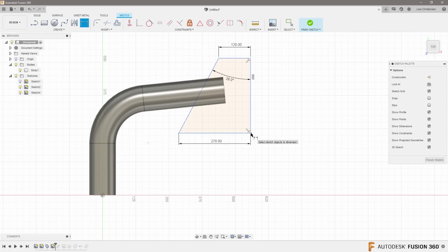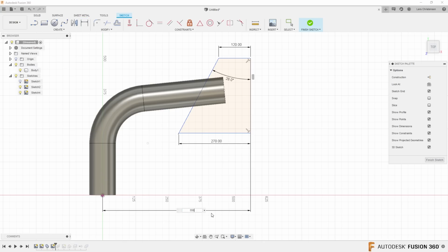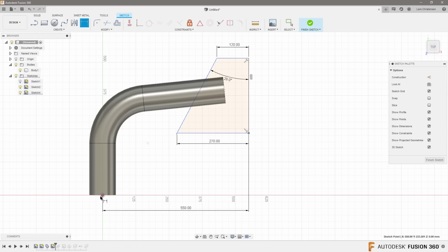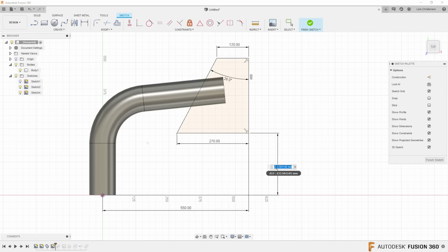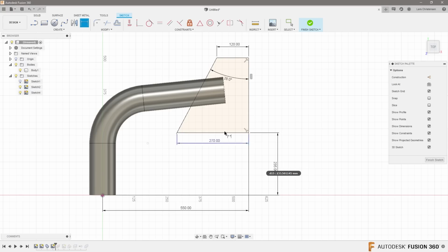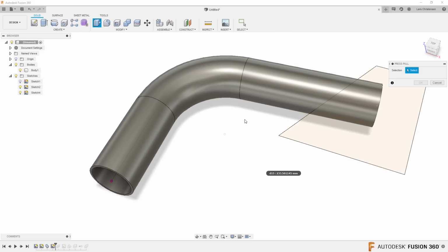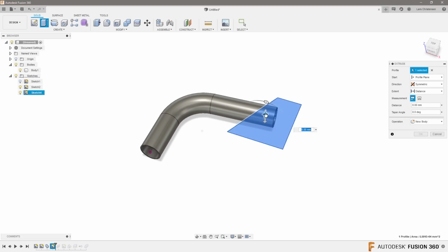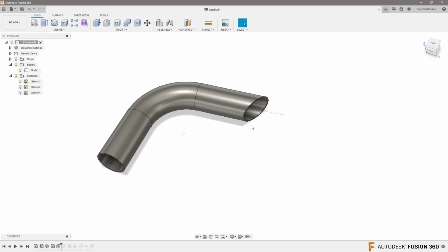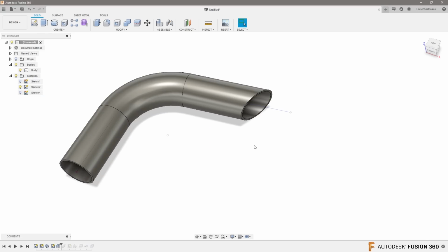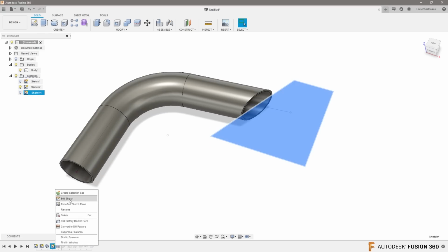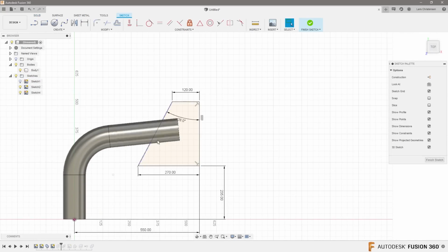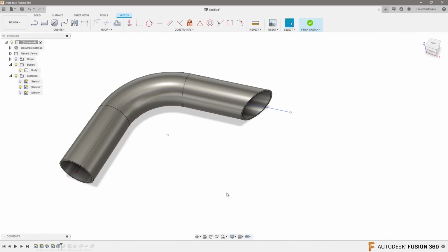But my point is that the angle dimension I just created is the one that is the most important one. See, now it's fully defined. This 28 degrees could be the one, and then you could do a Q, and then just do a symmetrical cut through here, and you will end up with the same thing as before. Now it's just this sketch that is driving that angular cut. That is probably what I would actually end up doing.